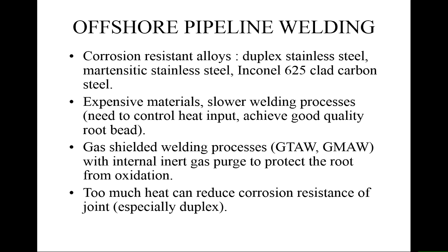And we use the gas shielded processes, the TIG and MIG welding, with an internal gas purge in the pipe to protect the root passes from oxidation for those. So these can all be done offshore, and the welding procedures can be set up for all these materials.